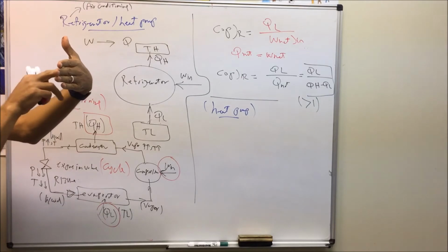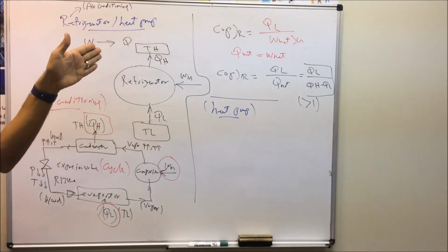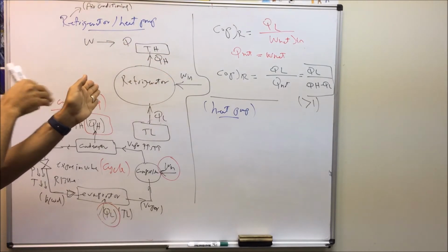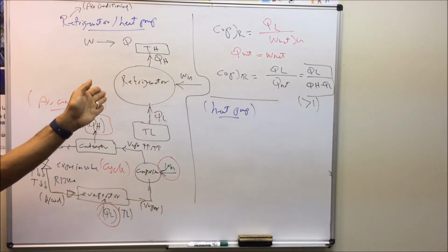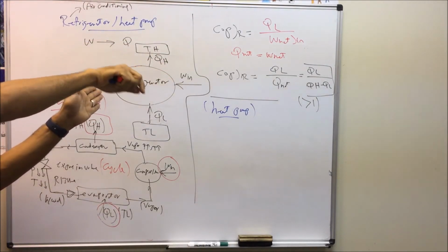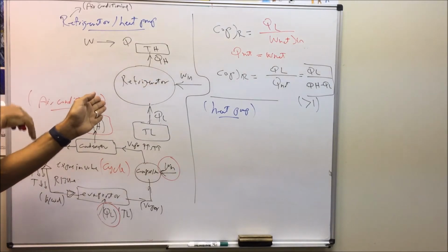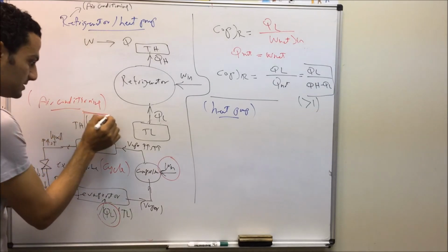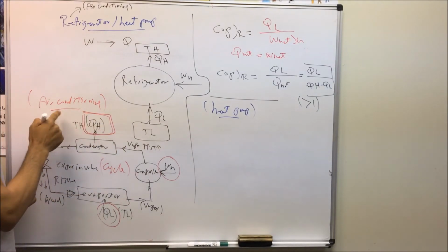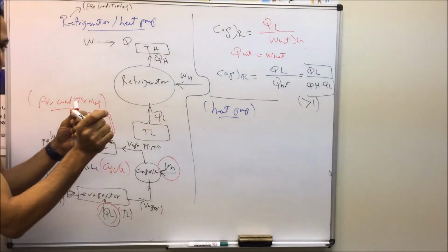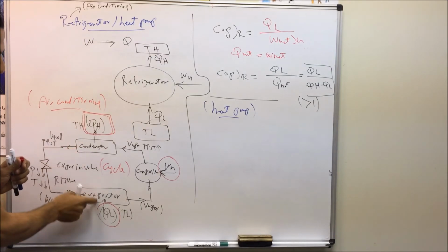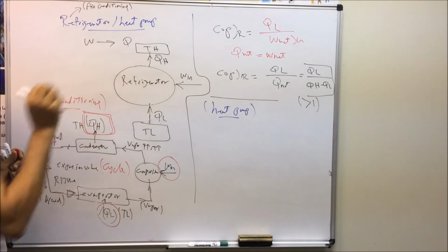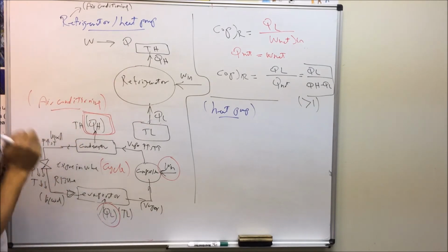What will happen if I just flip this air conditioning system? I will make the evaporator outside and the condenser will be inside. So in this case the heat will be absorbed from the outside and then it will be rejected inside. It is the same air conditioning system, I just flipped it. I made the condenser inside and the evaporator outside. So I'm doing the reverse in this case. We absorb the heat from the outside and reject it inside.